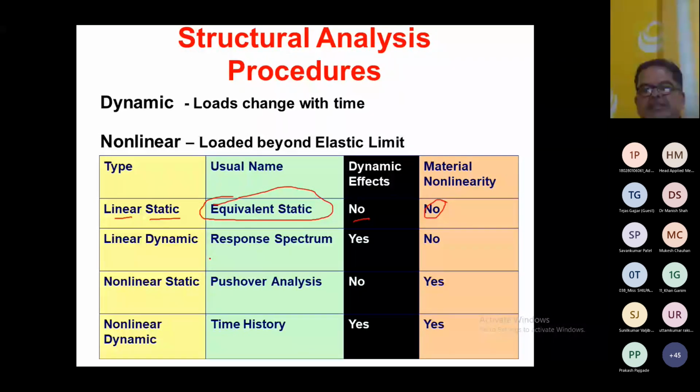Now linear means we are not talking about any non-linearity, but dynamic means we are talking about loads which change with time, right? So the dynamic effect we are considering in the response spectra. The nonlinear static, the pushover analysis, is the case of nonlinear static, right?